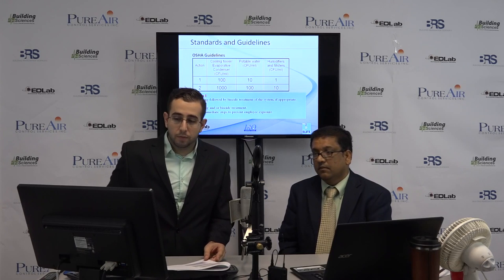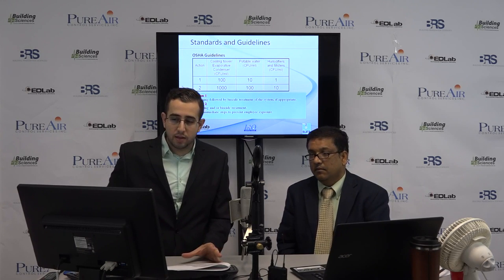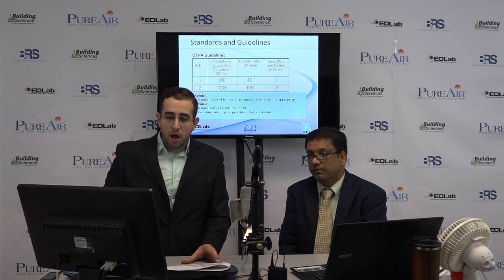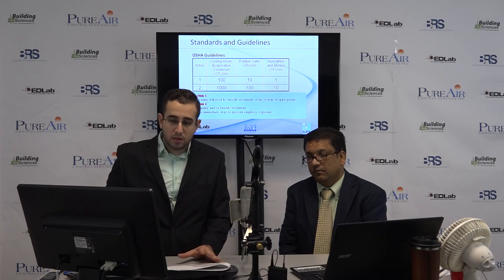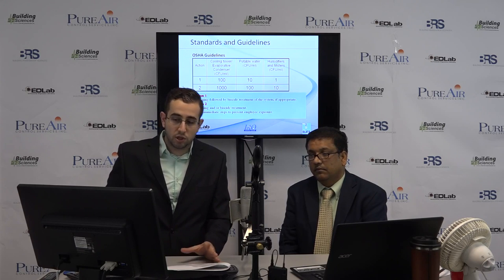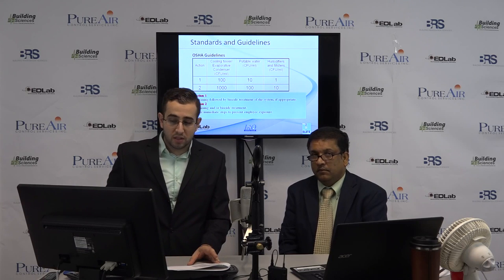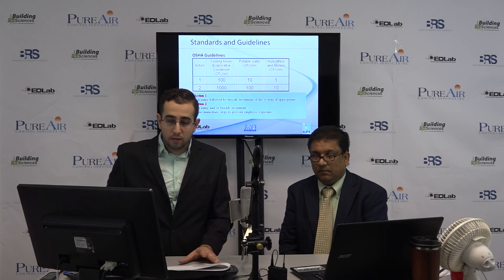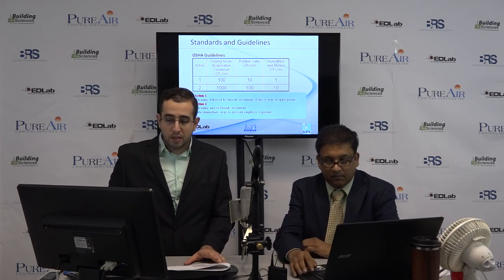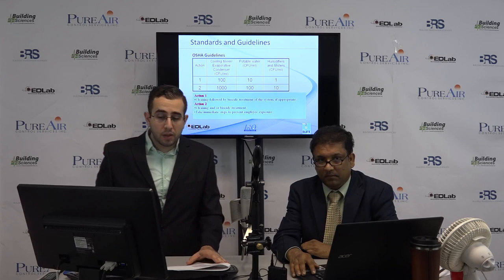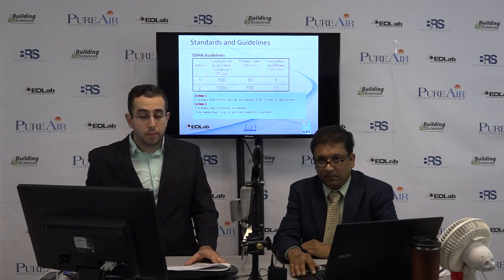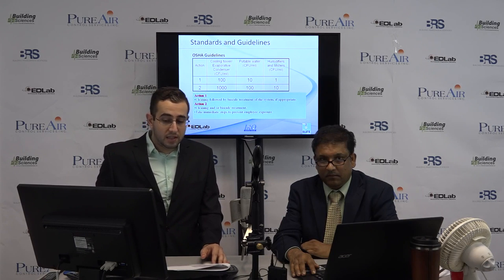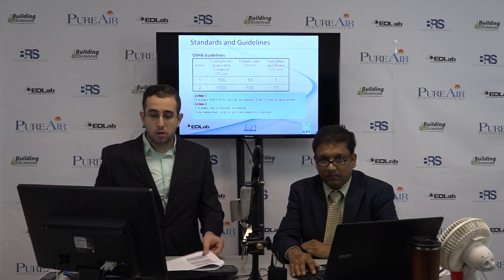As you can see here, for detection of Legionella within these different settings, whether the cooling tower, potable water, or humidifiers, we have action levels depending on how many colony forming units, which is what CFU stands for, are detected within those samples. At that first action level, if any Legionella is detected, it's just cleaning followed by biocide treatment of the system if appropriate. Action 2 is taken if there's a higher number of Legionella detected, and what needs to happen is cleaning and/or biocide treatment, and immediate steps need to be taken to prevent employee exposure.